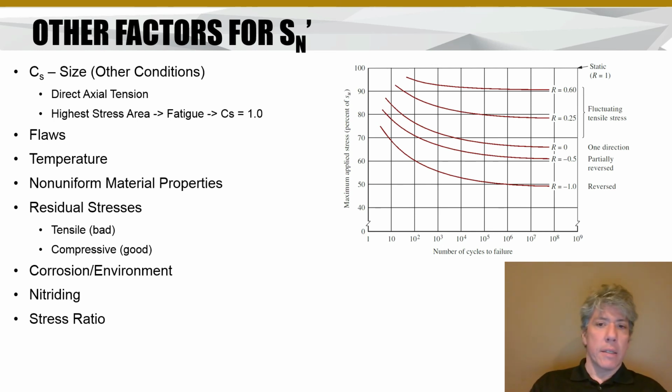Well, it turns out that, again, tensile stresses are really what encourage fatigue, not so much compressive stresses. And so really for compressive stresses, that's not near as much of a concern or something we're interested in with this type of diagram. Basically the curves would start to go back up, or they would just be at the static position depending on how the loads are applied and so forth. So we're really interested in tensile stresses. So the stress ratios we consider are those that include tensile stresses.